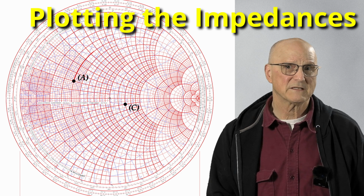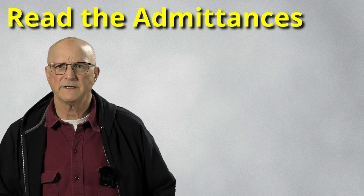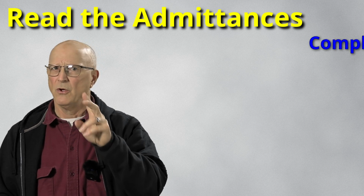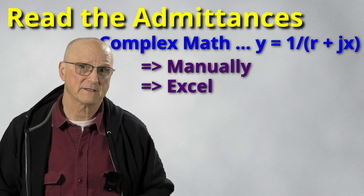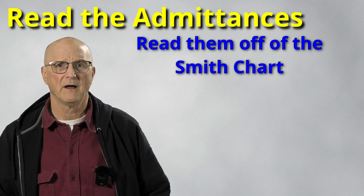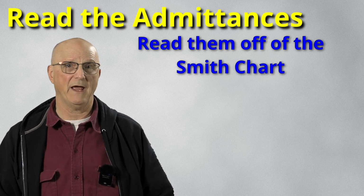With our two impedances plotted, we are ready to read the admittance values off of the chart. Well, we need to know the normalized admittance values of each of these to accomplish our goal. Now, there are two ways we could do this. We could do the complex math either manually or using Excel or using Octave. Or we could just read them off of the Smith chart. I'm going to read the normalized source admittance values off of the Smith chart and avoid the complex math.